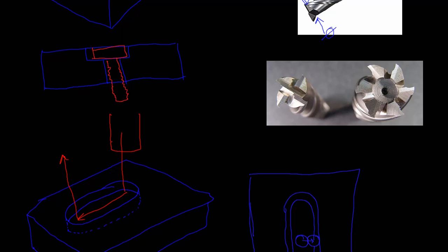And it's all because you are not actually cutting any material here. You're just ramming a spinning tool into the metal. It would be no different than taking a bar of this diameter, sticking it in the spindle of the machine, and plunging it into the top of the material. I bet you would be very unsuccessful in making a pocket.